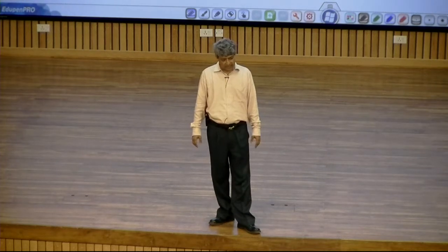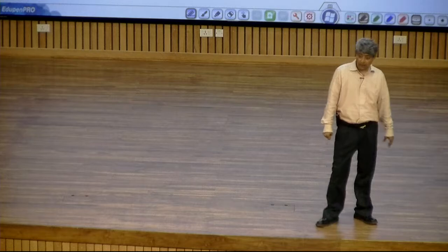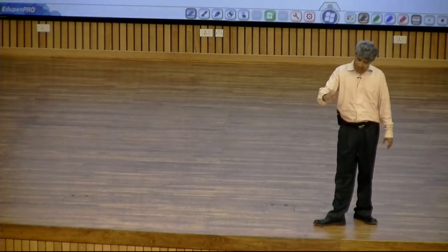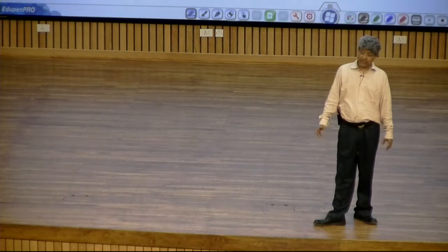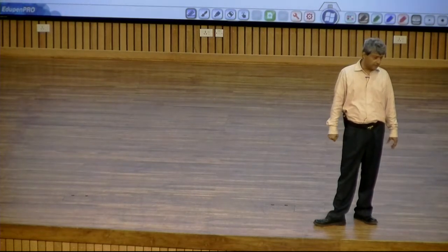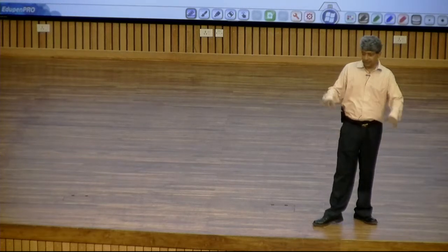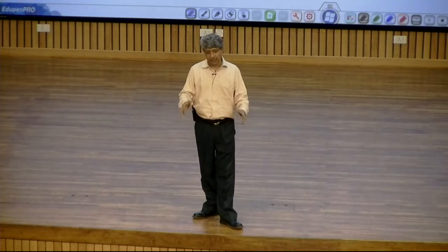In this book, everything is 20 degrees Celsius. For us, everything is 30 degrees Celsius. And there's a big difference in viscosity for water, oil. For liquids, it goes down. For air, it goes up. So these trends depend on the microscopic structure of matter. On the continuum scale, these are prescribed as material properties.